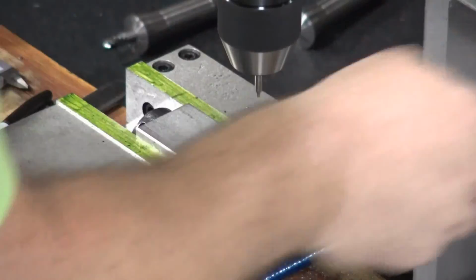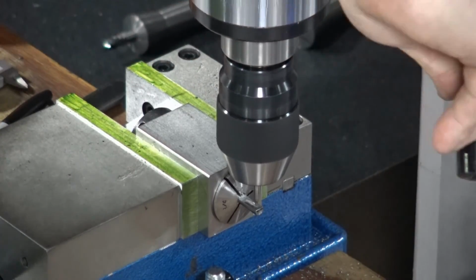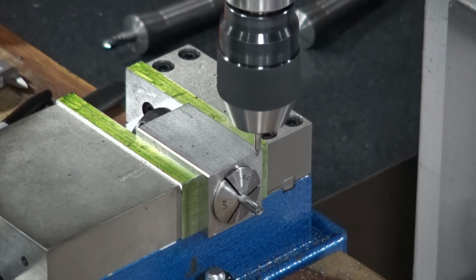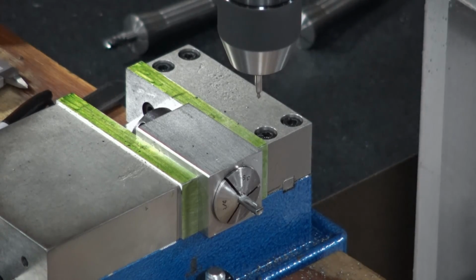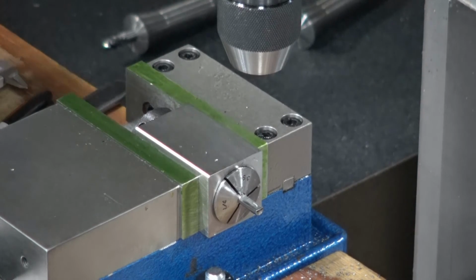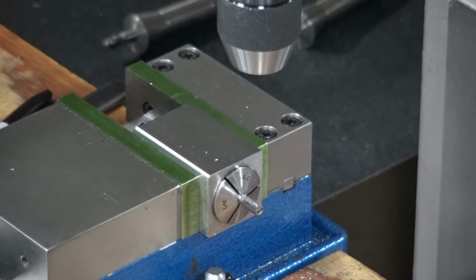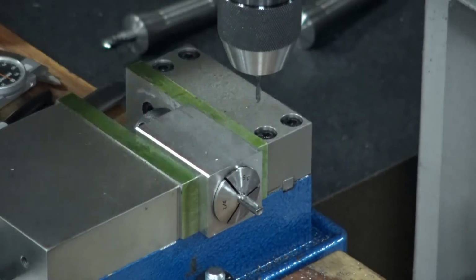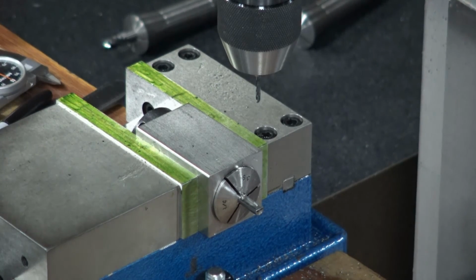So now I'm going to deepen up that center drilling. I deepen that up, now I'm ready to switch over to our drill bit. Again, we're going to keep measuring these things because we're too close to the end to mess things up now. Roughly 1/16, that's where we're at. That's the right drill bit. Calculate our RPM: 4 times the cutting speed divided by the diameter.